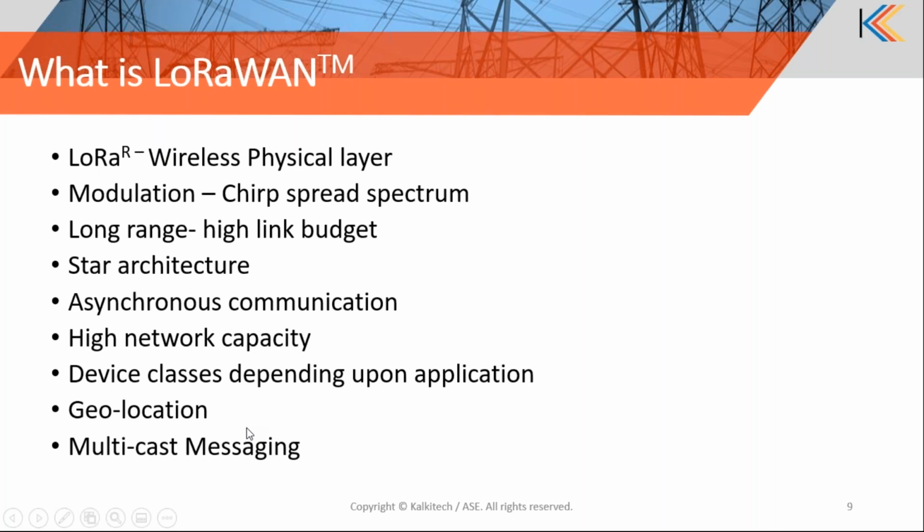If we have the location and the other identities of the devices, we can automatically register a device with the head-end system, and we can push the configuration from the head-end system once we know which device it is and from where it is connecting. So these are the specific advantages of LoRa, which will be useful for LV as well as MV monitoring applications.